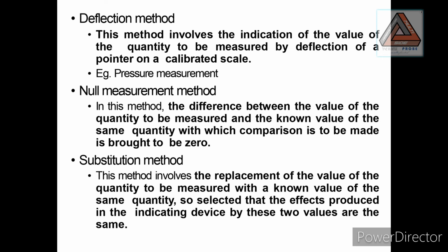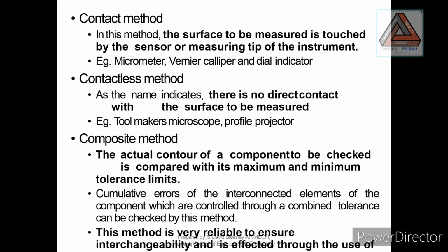So in the generalized measuring system, when we put the weight on the weighing machine, the mechanical weight is converted into an electrical input. The sensor senses it, the primary sensing element converts the signal, and the weight signal goes to the variable manipulation element. The variable manipulation element amplifies the signal, which is transferred to the data transmission element.